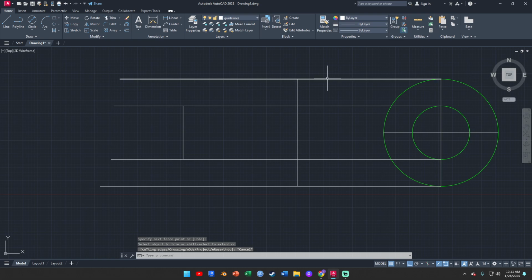So you see what the purpose of drawing the guideline is for? The purpose is so that you get this distance here equal to the small circle, and this distance here equal to the big circle, and it has to be in line with your circle, right? So this can't be slant, or oblique.